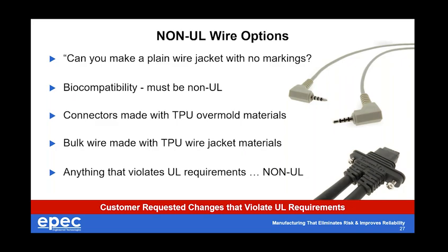At the end of the day, any of these requirements that our customer asks us to change that violate UL will trigger some comments or discussion with our technical team and you, the customer. We want to make sure it's clear to you and the certification bodies that you're working with that if UL is required, we must be fully compliant with all regards to the UL spec in terms of part marking, flammability, voltage threshold, and temperature performance.